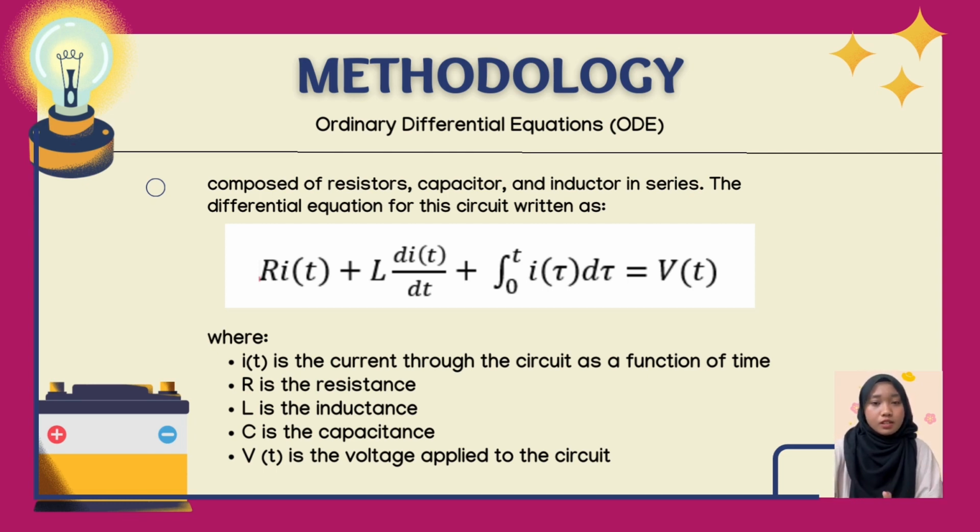So what I can say here, eigenvalues represent the natural frequencies of the circuits, while the corresponding eigenvectors provide us with information about the system response patterns. Together, they form a powerful pair in understanding the circuit's dynamics. The general solutions of the system can be expressed as a combination of the modal matrix P, constants derived from the initial conditions, and exponential terms based on the eigenvalues. These solutions provide us a comprehensive understanding of the circuit's behavior over time.